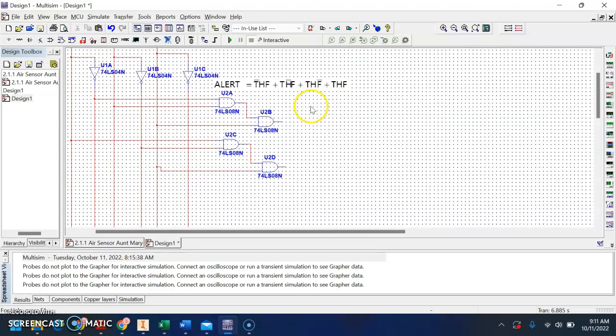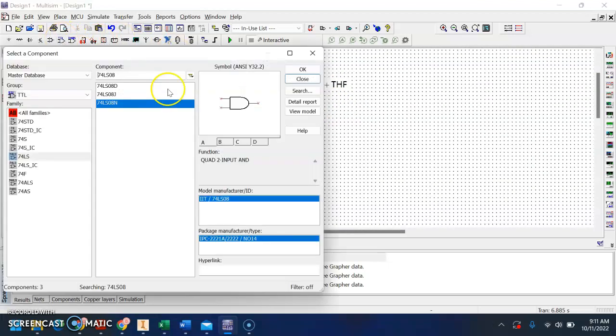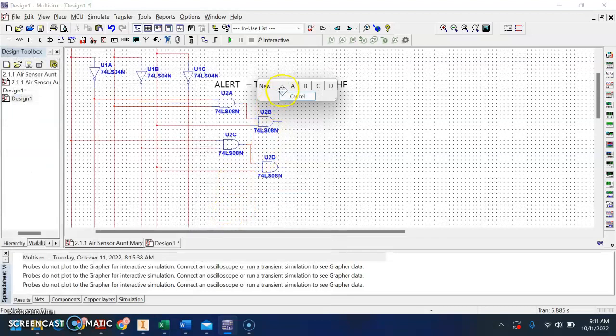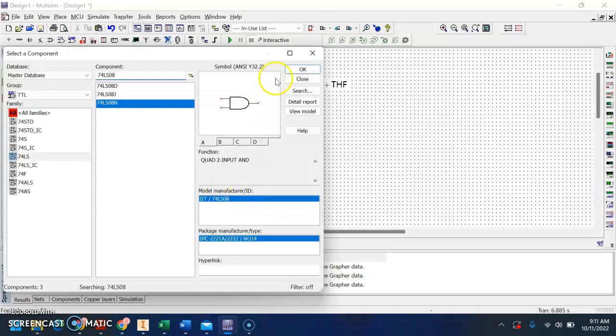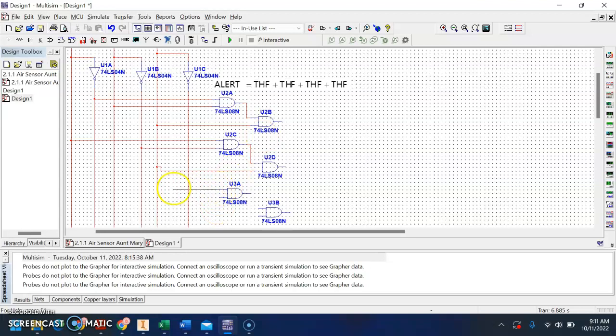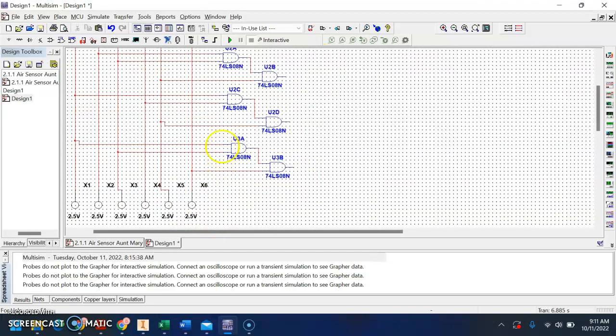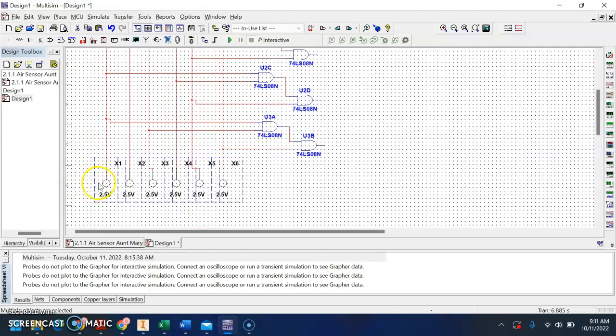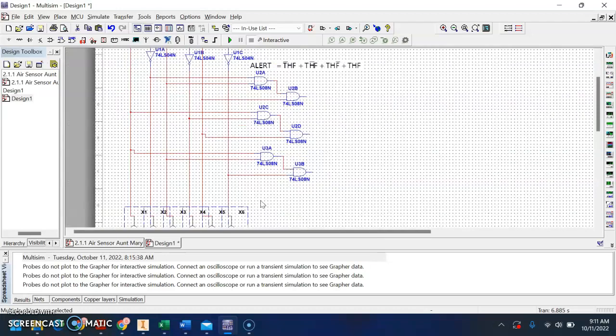Positive T and H have to get multiplied. So that is a 2 input AND on a new chip, placed right here. And then we have to AND it with the third thing. Let's see how that looks. Positive T, positive H. This has to get ANDed with not F, which is this one. Then if you need more bus line room, you pull these down.